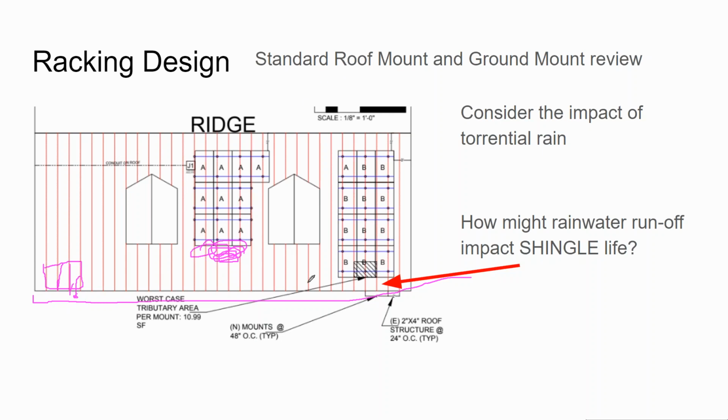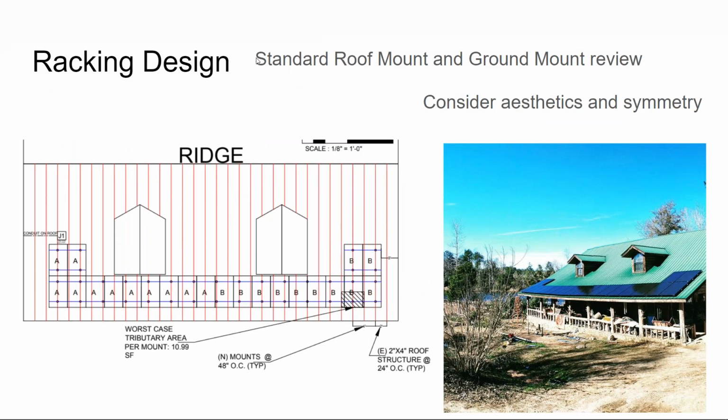In an area of heavy snow, it's kind of the opposite, where you want to defer to the top of the rooftop and really have the modules go all the way from the top of the roof down to the bottom, because you want that snow weight to be evenly distributed. You don't want it to mound at the bottom. You also don't want it to mound at the top. So rainwater and structural issues probably don't get enough attention in the industry.